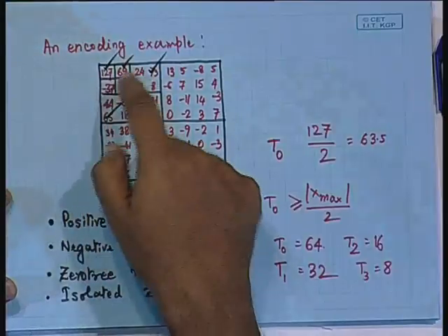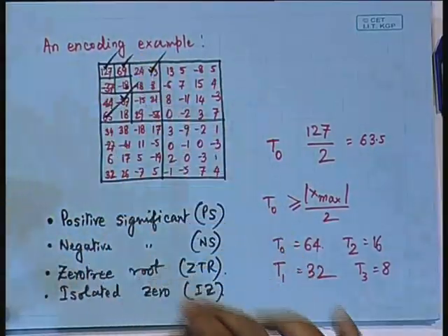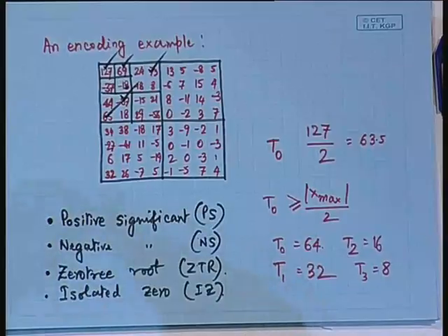What is the essential philosophy of that? Because if you have to generate an embedded bit stream, better start with a strictness, in the sense that only whatever are very significant, I mean at the end of the first pass you will be finding that only a few coefficients you would pick up as significant, and those will be encoded, rest several coefficients would be treated as 0 tree roots, and we do not have to encode that.